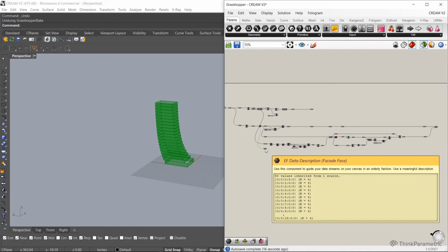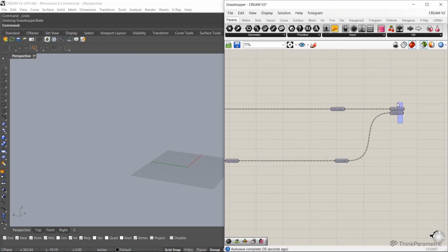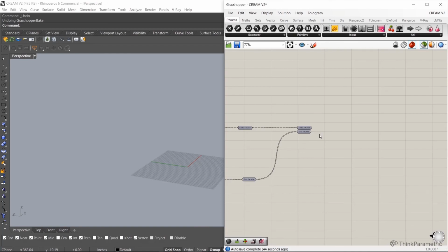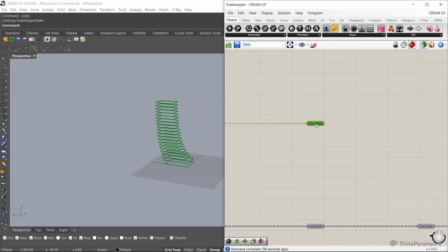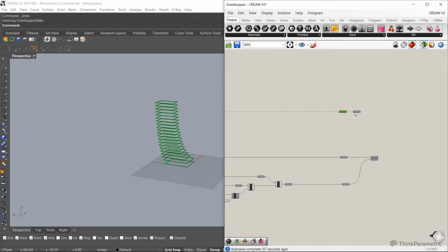So, you can obviously add 3, 4, whatever stages you're coming out of. Let's say there's 2 or 3 ideas that are still in the mix. We can keep these here, and then we can choose which one we want to use in order to output the information that we need to move across to our Revit world through the script there. I'm also going to bring a floor outline. So here I'm just creating a break in the script. So basically at this point, this little chunk that we just created, essentially it's this part here. We're creating our facade and our floor plates.